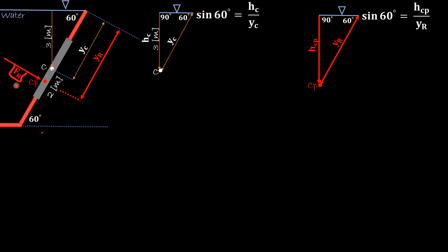So let's see what we have to do here now. We want to find F sub r. Now, we know that pressure is force over area, correct? So here we will solve for the resultant force. We take area to the other side of the equation, so it will be pressure times area. And we know that pressure is what? In this case, we are dealing with hydrostatic forces, fluid forces. This expression, we know it as the specific weight of the fluid times the height.